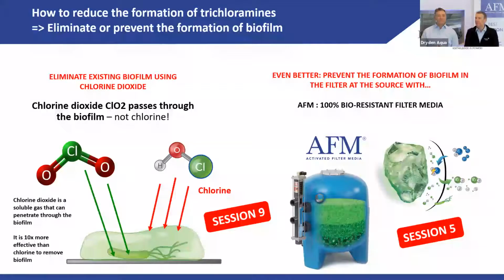One is the elimination through the use of chlorine dioxide. Chlorine dioxide will penetrate the biofilm. Chlorine will not. This we will talk about in session 9. Or even better, prevent the formation of biofilm in the filter with the use of AFM, because AFM is 100% bioresistant, no biofilm. We'll talk about it in a week from today in session 5.